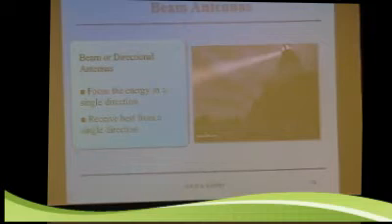If you double your power, that's great, but that only helps when you transmit. If you get an antenna with 3 dB gain, it also has a 3 dB gain in receiving, so you can hear better where the antenna is pointed. So that's another reason why an antenna can be a better investment than an amplifier. An antenna can be your best investment because whatever gain you get, you get both ways, transmitting and receiving. If you get an amplifier, you just get it transmitting.